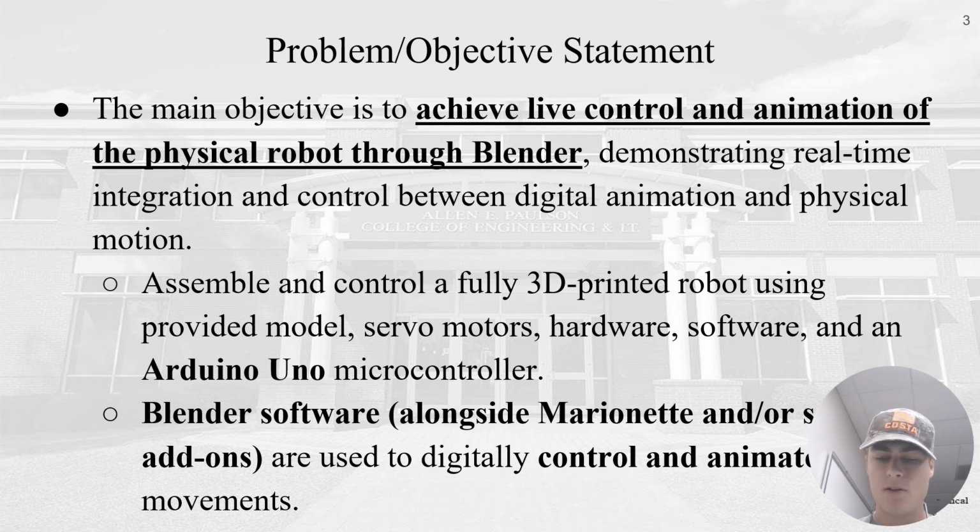And we went between two different add-ons for the software, which were Marionette and Servo add-ons. Both were pretty promising, but we ended up going with the Servo add-ons because they supported our driver setup automatically. With Marionette, we had to do a lot more software manipulation and coding to get the drivers to work, because Marionette was originally designed to only be used with the Arduino, not using the drivers.